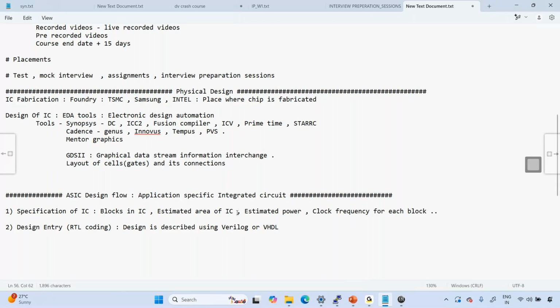Yeah, that is true. So I thought the chip size we can decide based on the foundry. Whatever chips, a mobile phone application chip, you would think it is very simple, right? It's very complicated. The area will be more than the limit given by the foundry. The foundry will tell, okay, minimum IC area should be this much. It should not be less than that. If it is less than that, then we cannot fabricate. That is the rule given by the foundry.